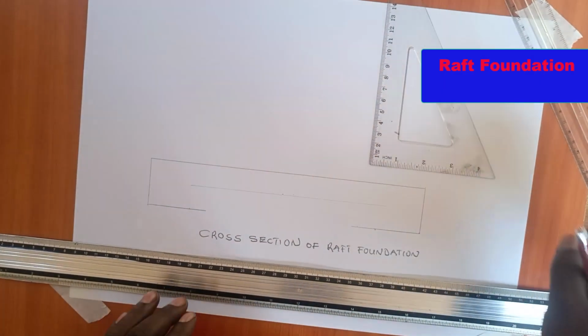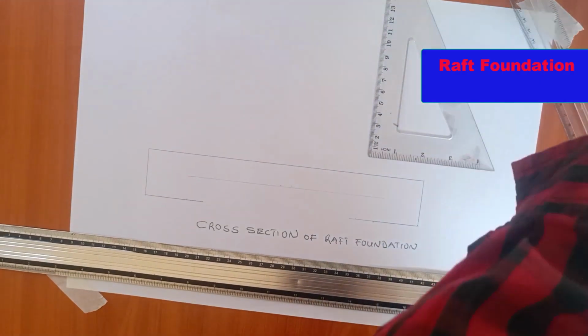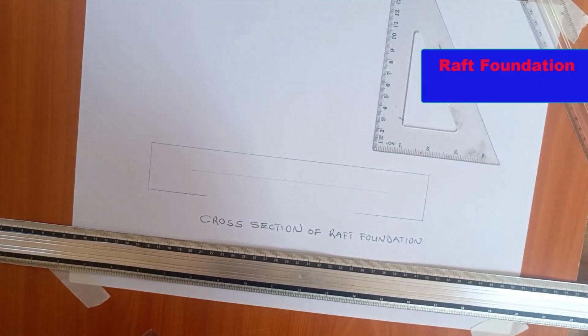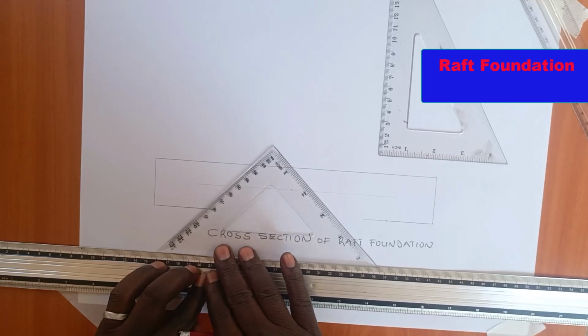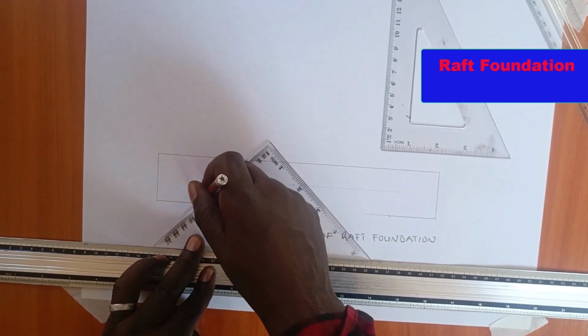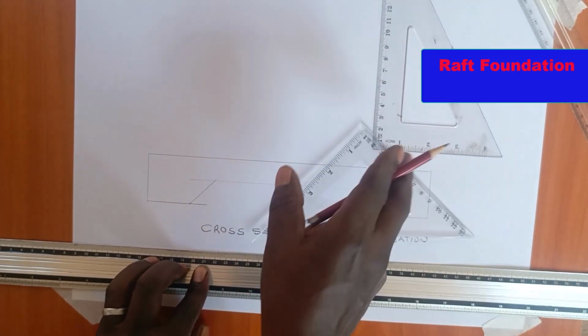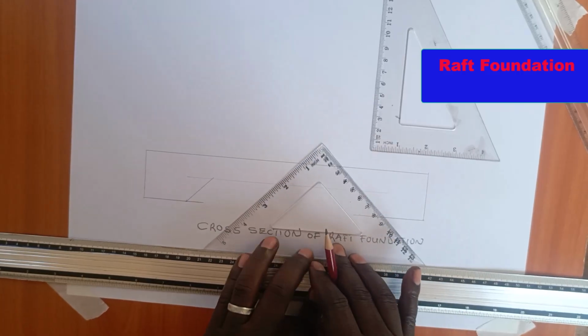Yes. So now I'm going to use 45-degree set square. I'm going to use 45 degrees set square to extend this expanded base. Where it meets there, that's the point I need. So I turn this side also, I do the same.